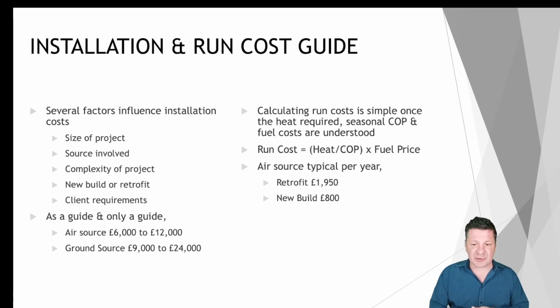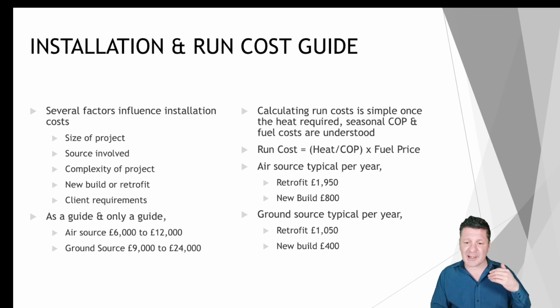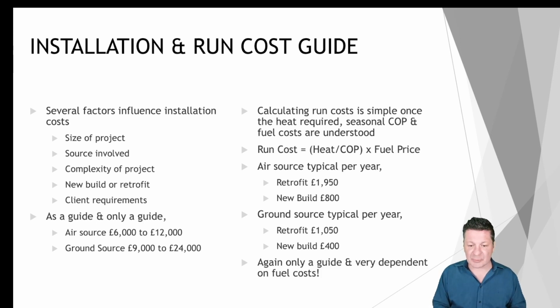To give you some numbers again to conjure with, and again, very rough numbers, an air source in a retrofit will cost something like £1,950 a year to run. For a new build, something like £800 a year. And again, a ground source retrofit, just over £1,000 a year, and a new build, something like £400 a year. Very much depends on the size of the property, and again, this is for a typical domestic installation. Very dependent on fuel costs, as I say, and very, very much a guide.